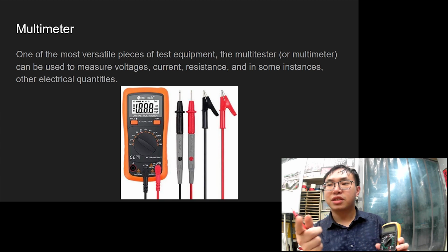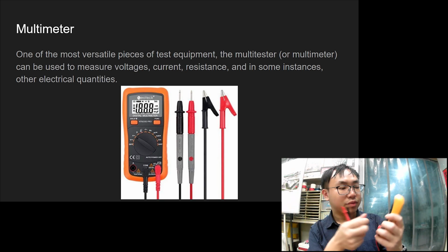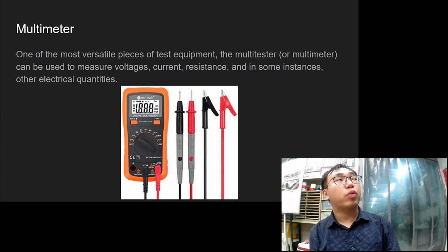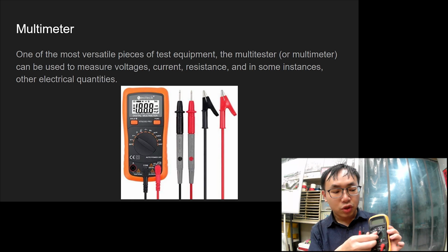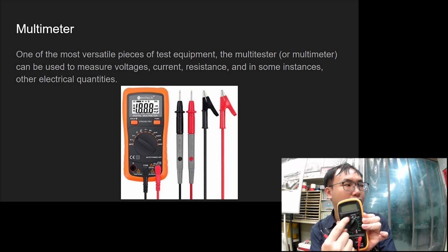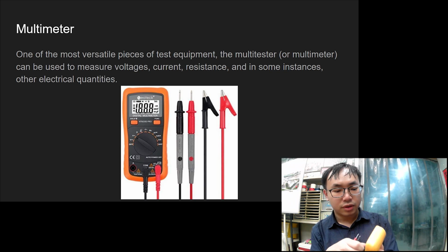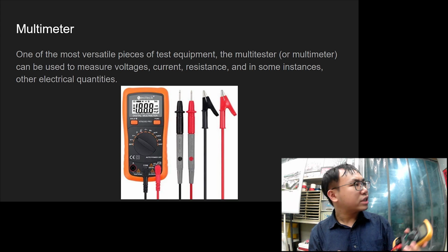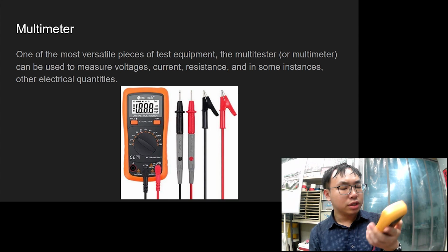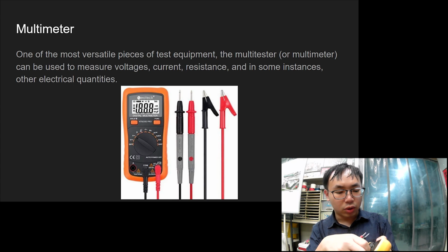Still remember what RMS is? Root mean square, which is what we use when we want to compare the actual voltage that can be used in AC, the equivalent voltage of AC compared with DC. Only the AC mode will help you measure the RMS instead, and it prevents the inaccuracy.